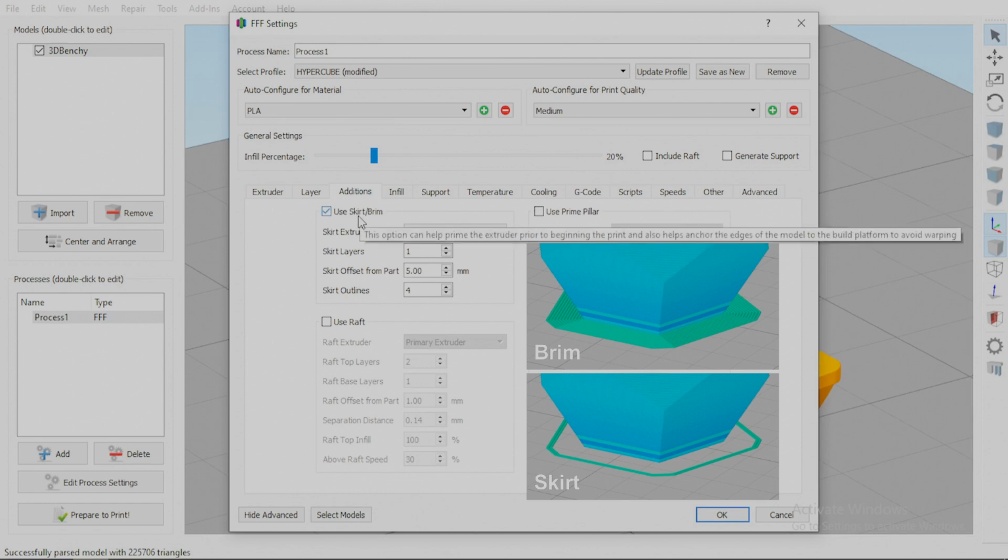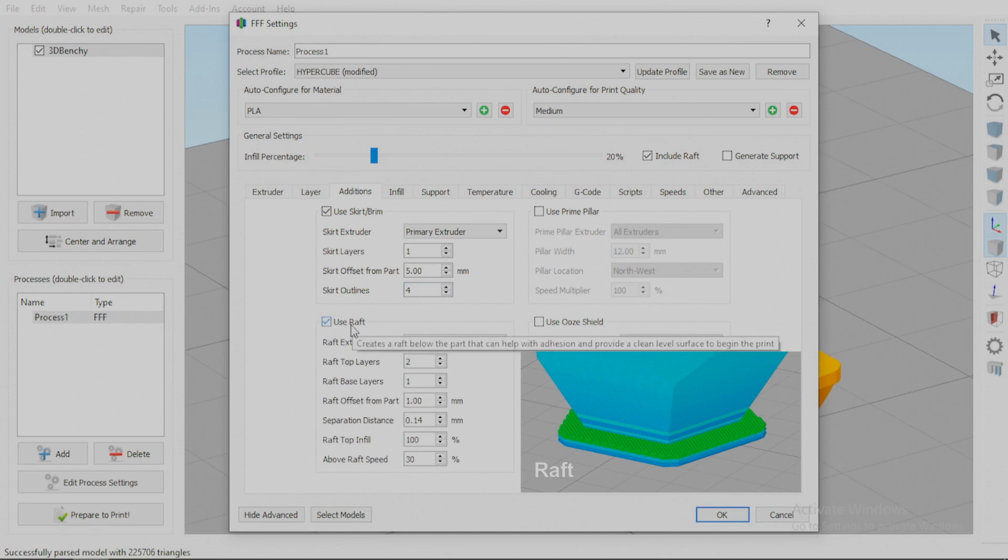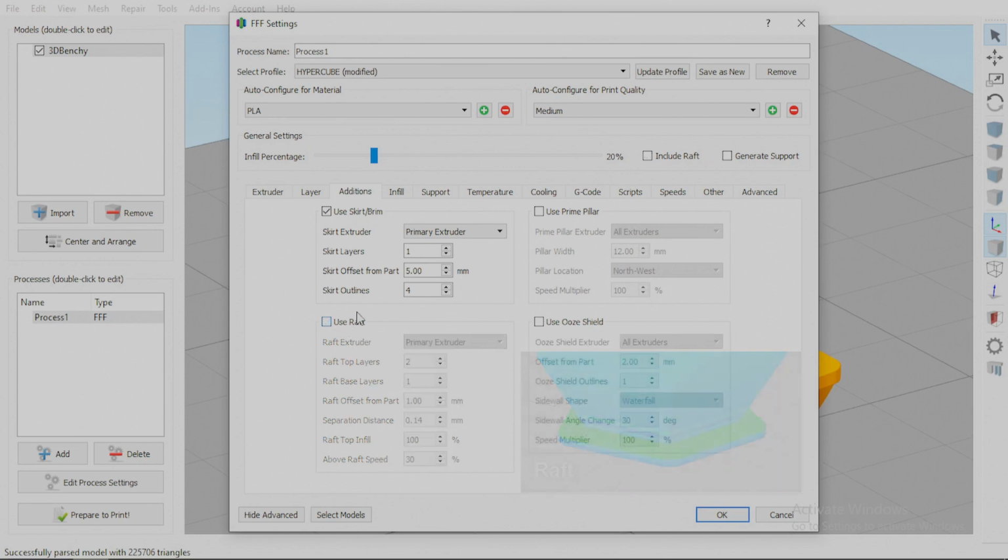One of these is used to increase the adhesion of the printed object to the print bed. When printing small or thin objects, it is recommended to use a brim. It's an additional flat surface that will prevent the object from warping or detaching mid-print. It can be easily removed when the print job finishes. Raft is a special kind of support structure which lifts the whole printed object above the printing platform. It helps to prevent warping or lifting the object from the print surface.